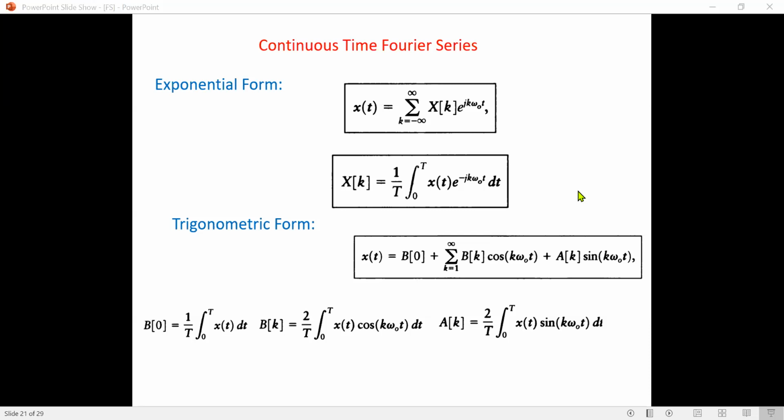form, isn't it? Can you see the trigonometric form here? Yes, sir. So this is what the trigonometric form actually is. You see that no matter by which ways your constant terms are defined, mathematically they are same. When we use trigonometric form, the trigonometric functions such as cosine and sine omega t are real functions, and they will be associated with some Fourier constants, say bk and ak. They are also real, but they are the function of harmonic number k.